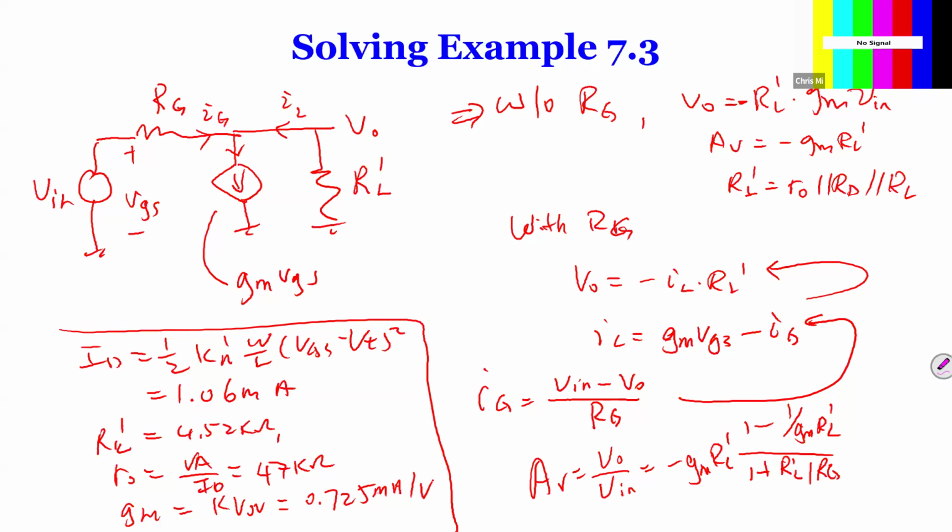So finally, we got VO, I don't have the number. Okay, so I think we're going to stop here. You can plug in numbers to get the actual number. As we move on, we're going to see more and more examples, and some of them are fairly easy, sometimes more difficult, but we always follow the procedure. Find the MOSFET or BJT, draw the small signal equivalent circuit, find the components connected, solve the circuit. That's it. Okay, see you next time.